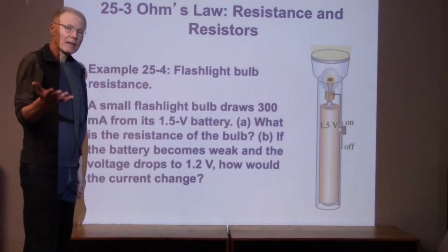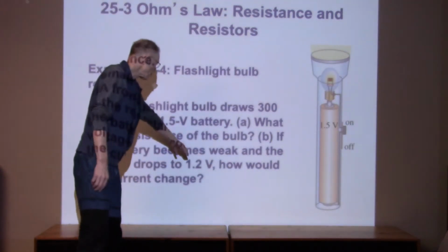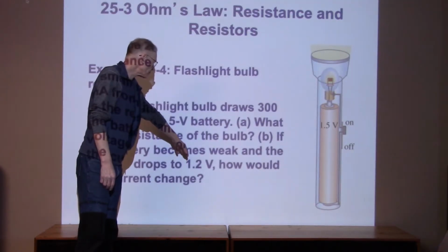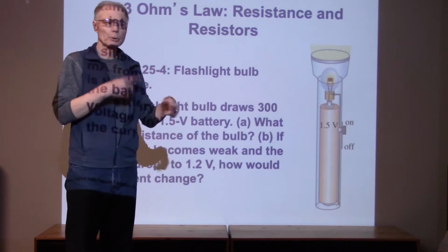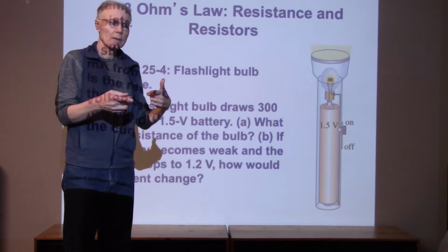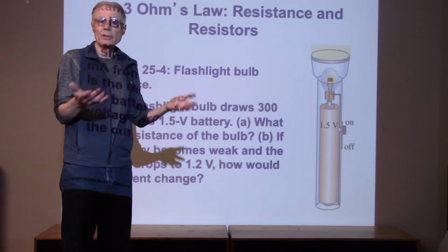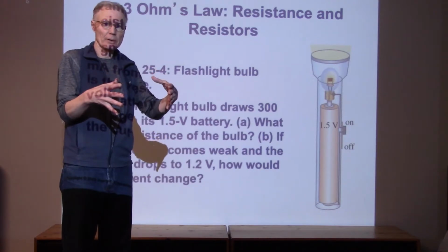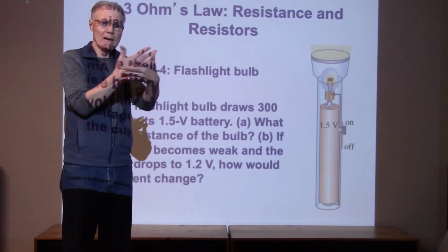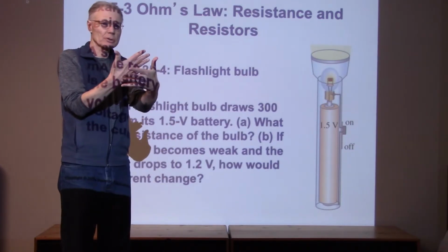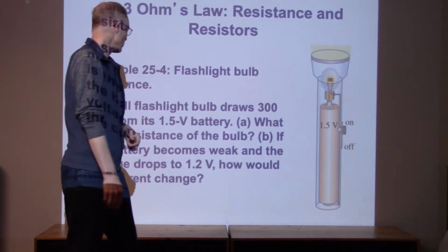And so you can have a drop in the voltage, especially when you ask a battery to do a lot, right? If you ask the battery to produce a lot of current, the current that it produces is going to depend on how much surface area there is where the reagents inside can react and different compounds can transfer back and forth.